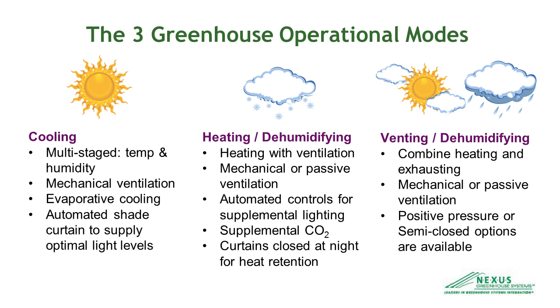These are important controls that are not so much to do with the climate inside the greenhouse, the temperature inside the greenhouse, but more to do with how you would operate the greenhouse in a closed environment. And then lastly, we have closing our shade curtains at nighttime in the heat mode, because this shade curtain also acts as a giant heat blanket for the greenhouse, helping keep the infrared heat back inside the greenhouse at nighttime when it otherwise would be radiated out.